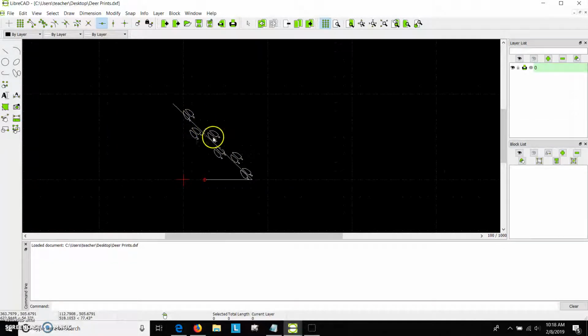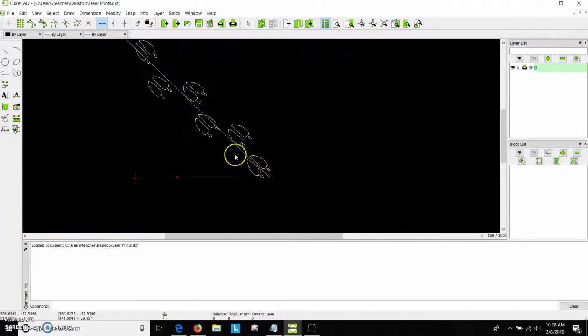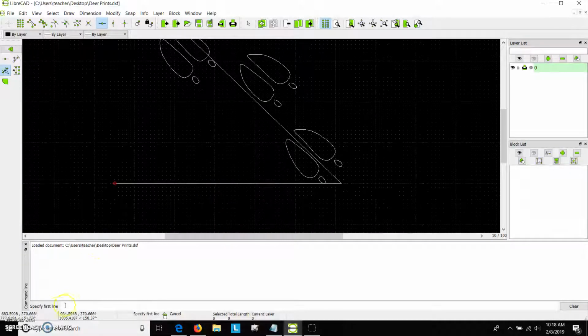Unfortunately, free rotating in this program doesn't really work. Trying to rotate something visually so you can watch it and align it by eye, it wants to rotate mathematically. So we've given ourselves 2 guidelines. Let's choose the measurement tool and choose measurement between 2 angles. It says choose one line right here, specify first line, specify second line, and it's reporting a minus 43.45 degrees.